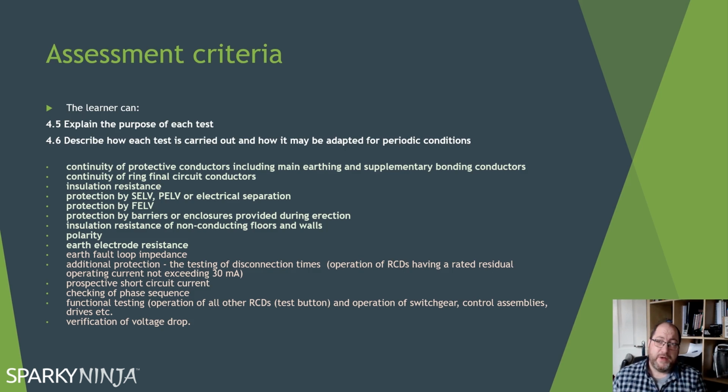What we're not supposed to do is go to the source, the voltage is 244, go to the end, the voltage is 236. We're not supposed to do it that way. We're supposed to actually measure a resistive value and calculate the equivalent volt drop. That's what we're supposed to do there. Okay.